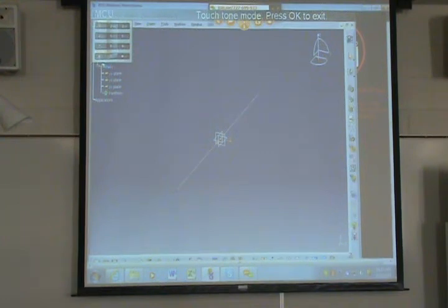You can kind of think of it this way if I do a little diagram for you. So when you do bottom up assembly, you kind of start creating parts, right? So these are representative of part files. You'll kind of constrain them from bottom up assembly. So you'll bring in parts one at a time into a product, kind of to tell it where the constraints are. So you'll create like a sub-assembly, and then you'll have like a master assembly file. So this is the first thing you do in bottom up. This is the second, and that's the third.